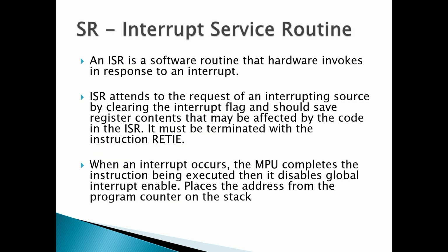ISR, interrupt service routine. An ISR is a software routine that hardware invokes in response to an interrupt. The ISR attends to the request of the interrupt source by clearing the interrupt flag, and should save register contents that may be affected by the code in the ISR. It must be terminated with the instruction RETFIE.